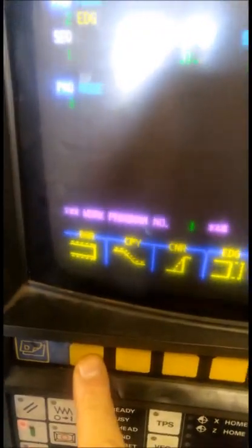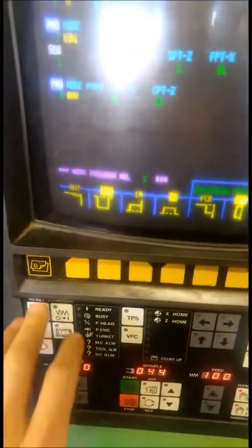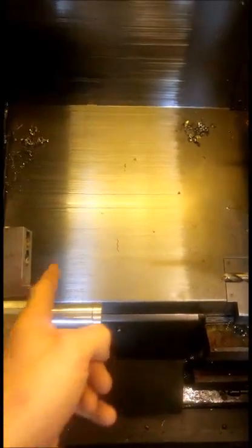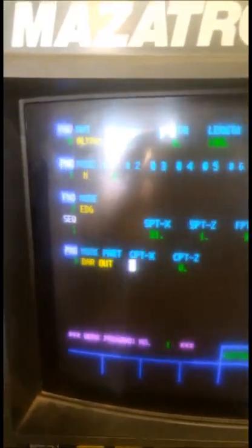Okay, next we're going to do a bar operation, and we want to do an out. There are two different sorts of out and two different sorts of in, two different sorts of face. The first out is when you're starting from the end and going out. The second one is if you're, say, starting back here and doing something. So it just changes the way that it rapids to where it's starting. So that's an out. Cutting point, again, that's just the largest bit where you're starting from. So I'm starting from 31 and 0, which will be that corner once it's faced off.